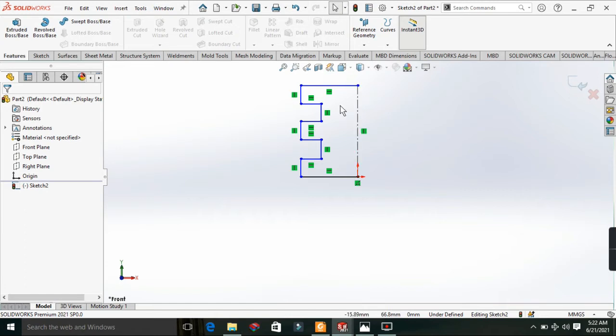So this sketch we are drawing here is an open sketch. Solid revolve will ask if you still want to revolve it, because for you to revolve with the features, the revolve boss, you have to have a closed sketch. Surface revolve is for you even though it is open, because it is called surface revolve. SolidWorks is very easy.